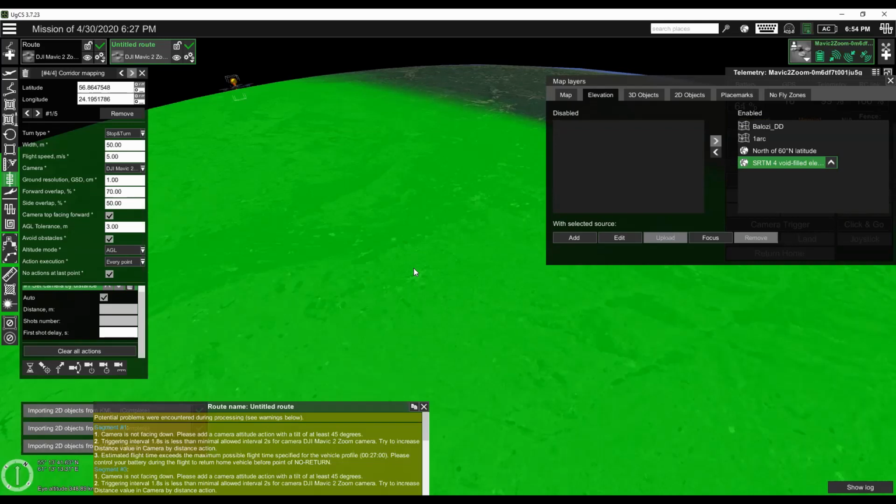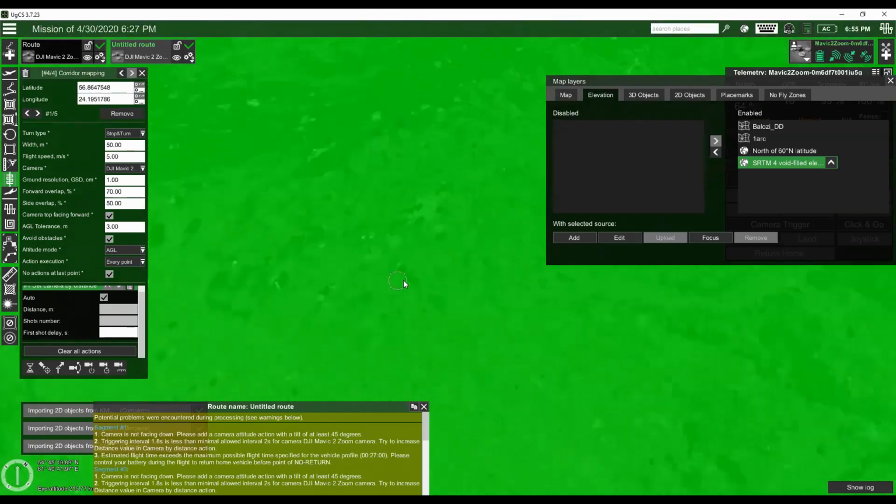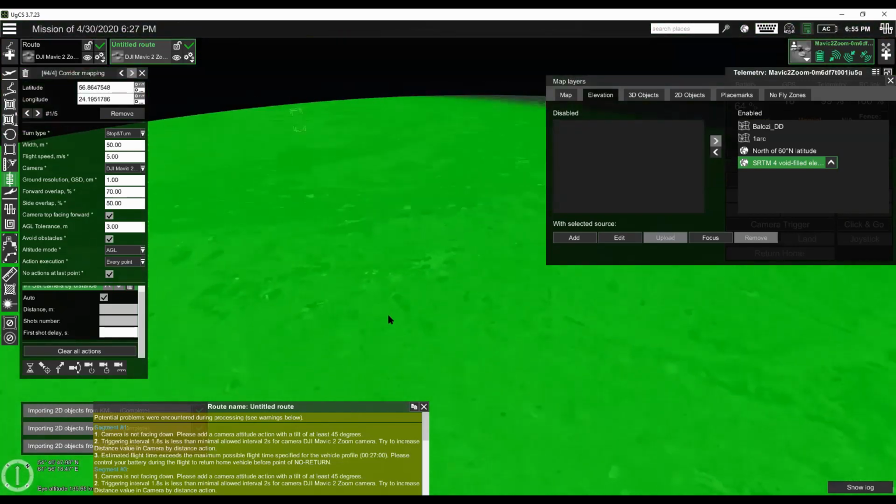Next question: are the waypoints calculated by difference to the position of the home position or by real difference to the terrain? The waypoints are calculated by the terrain elevation data. But the brains of the autopilot during the flight still rely on its takeoff point, 0 altitude.